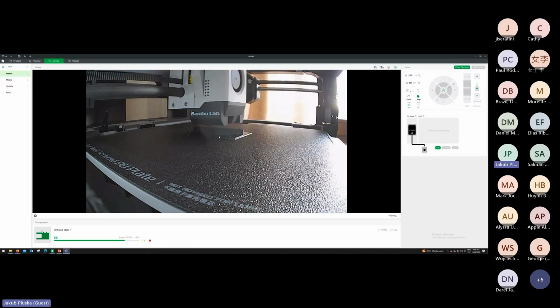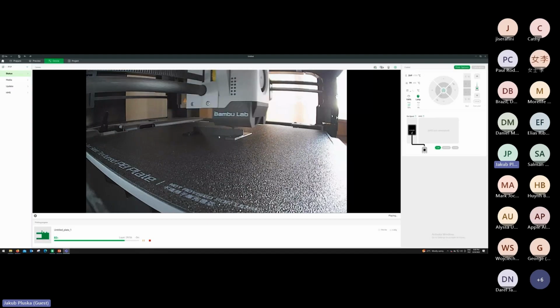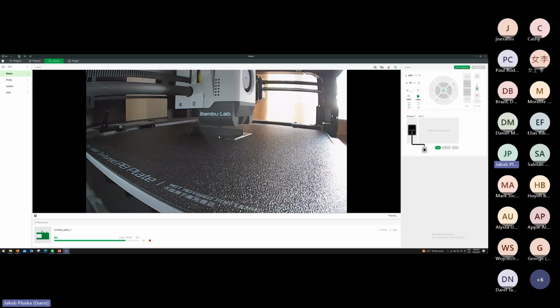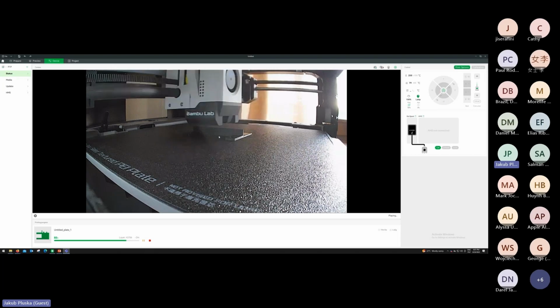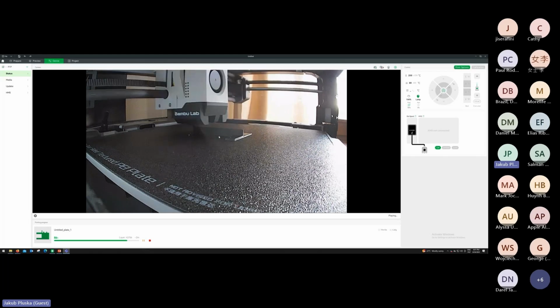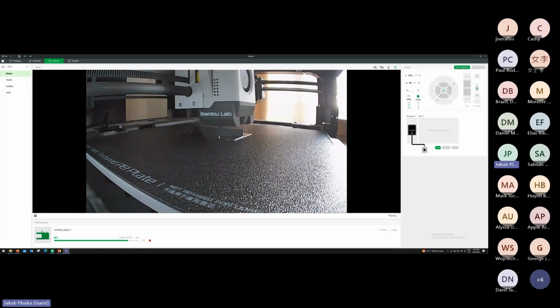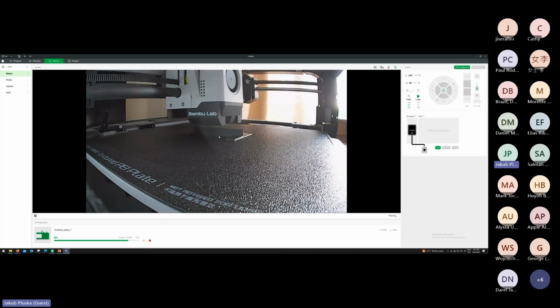Yeah, Paul, regarding the extruder, I'm using 0.4 as a standard one. 0.2 may have problems, and you have to clean it up. But the bigger extruders should be fine without any problems. So I would say it depends what you are printing, right? I'm using 0.4 right now, and no issue so far. Even last time I printed the mounting bracket for the iMac Studio for my colleague, printing for 6 or 7 hours, without any problems.